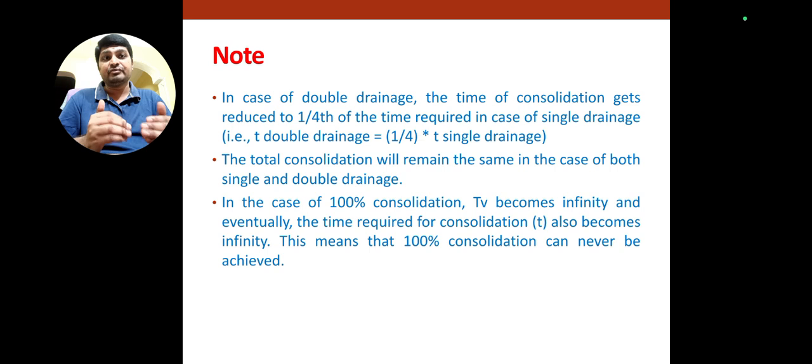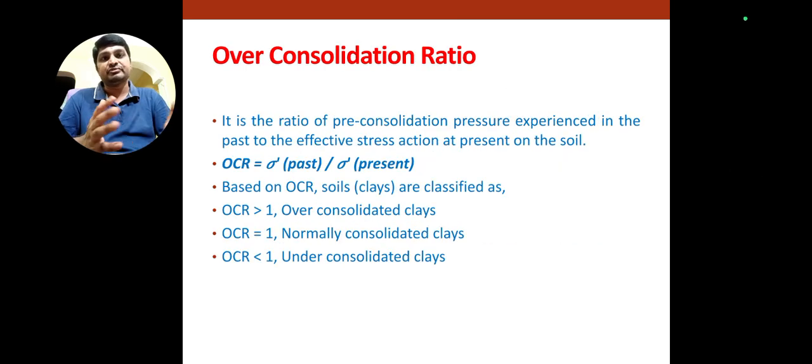Because the consolidation process means the pore water pressure comes down to 0, that is the meaning of 100% consolidation. When this takes place, the settlement takes infinite time, and 100% of the consolidation takes place.